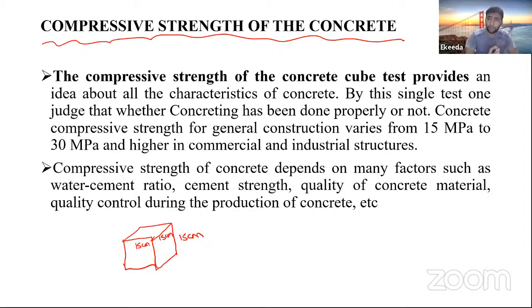After 7 days, 14 days, 21 days and 28 days of curing, we will take that concrete cube and place it in the compression testing machine or the universal testing machine, that is known as UTM.